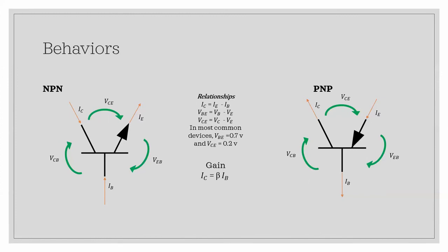We need to find a way to reduce the current because we don't want to start shoving in more current than what our stuff can handle. But if we need more current to power something, this is good. Many times when we're attaching a motor to something, the motor is going to require a certain minimum current to work, and using transistors effectively is key because of this gain.